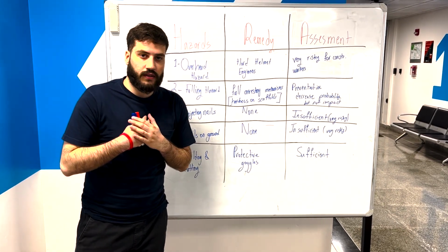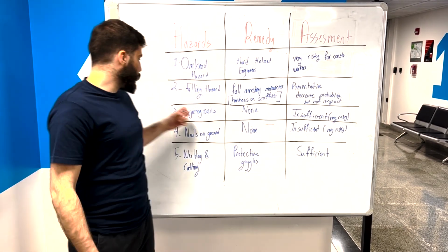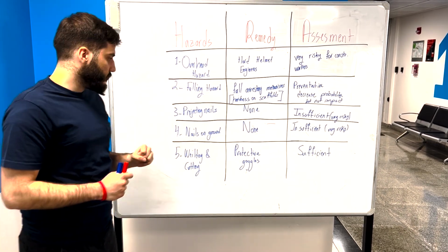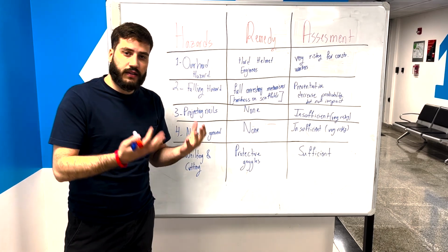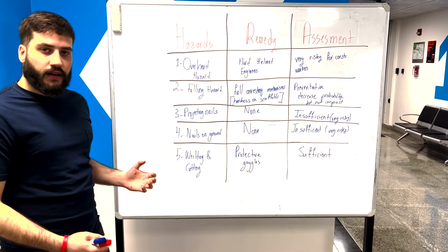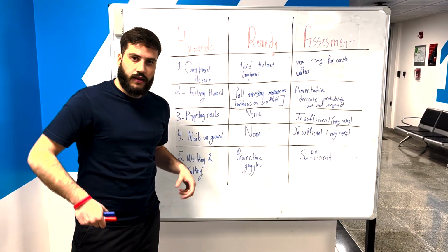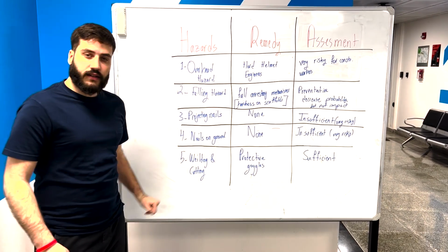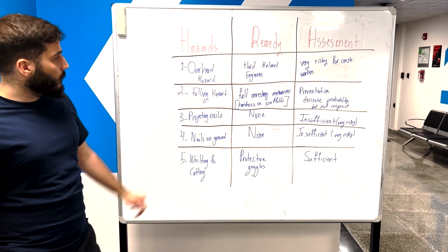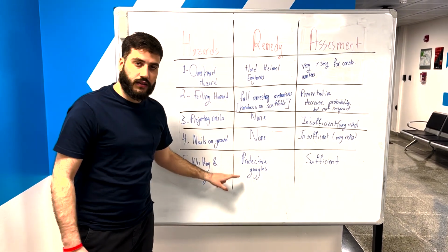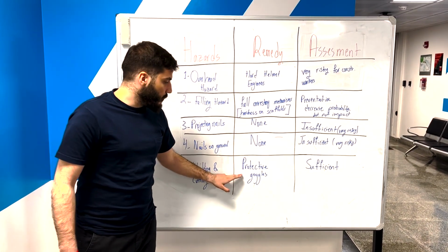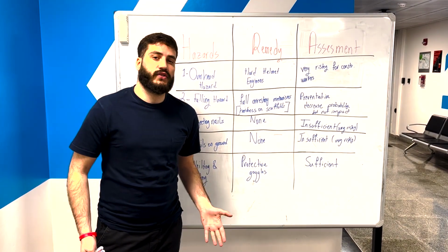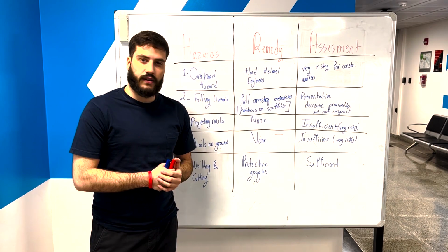And our proposed solution for these 2 hazards is to hammer the nails so that they are not projecting anymore, or to provide workers with safety boots. As for the welding and cutting hazard, the implemented remedy was to provide workers with protective goggles, which we believe is more than sufficient for site work.